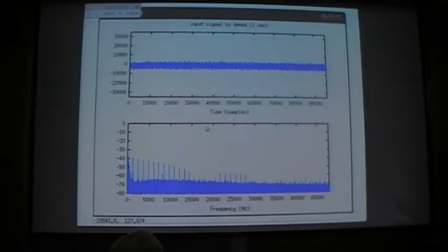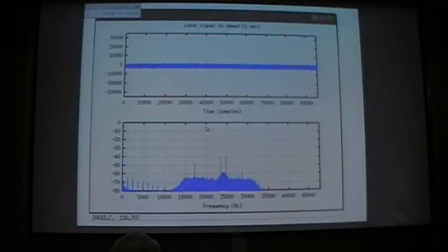So the microcontroller is sort of sitting there, suddenly gets an interrupt, does a lot of work, goes to sleep again, and that's causing a chunk of power to be consumed through the power lines, which is getting into the analog side. I think the thing's got 150 odd, I forget how many dB gain, but anything that goes wrong with that sort of gain in it, you get something turn up at the analog digital converter. So anyway, hunted those down and then pushed these down a little bit with some power supply filtering, which gave us something like this. You can see these have now been pushed down 30 or 40 dB. They're still there on the edge a little bit.